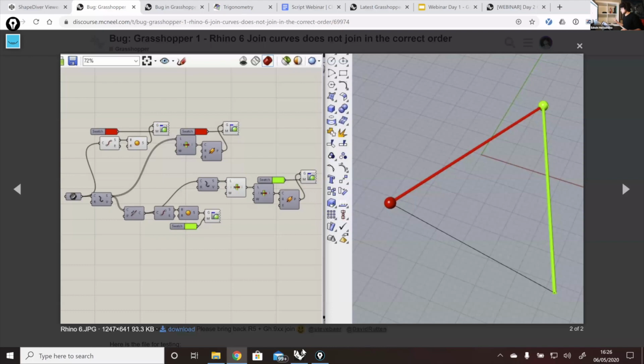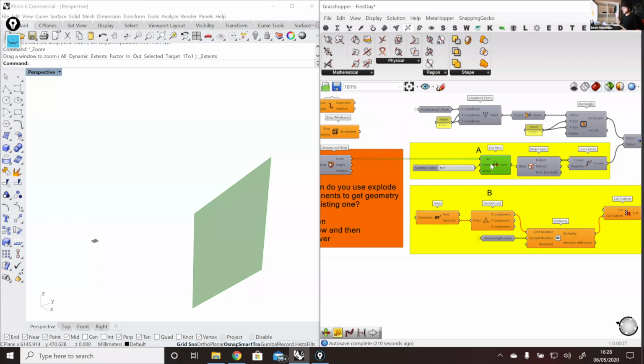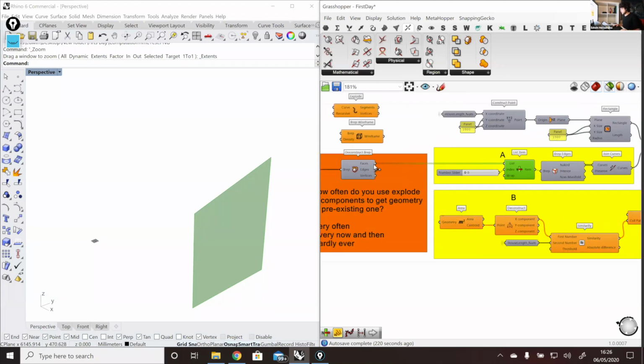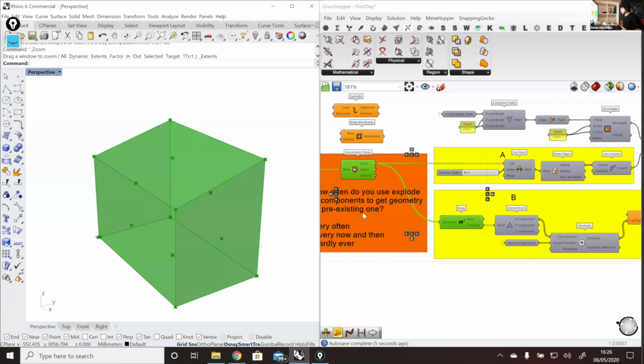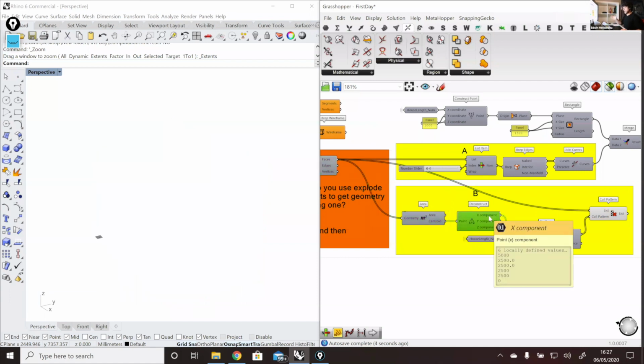So what I mean by geometry checks is this option B that we have here. Option A is to just simply say number 0. Option B is to actually do a geometry check before you pick something. So here, I take my face and the area of this face, and I just want the centroid of my faces, the point in the middle of each of these faces. Then I want to pick the centroid that is in the X coordinate in the same location as my house length, because I know that this wall is the one on the other side of my house.